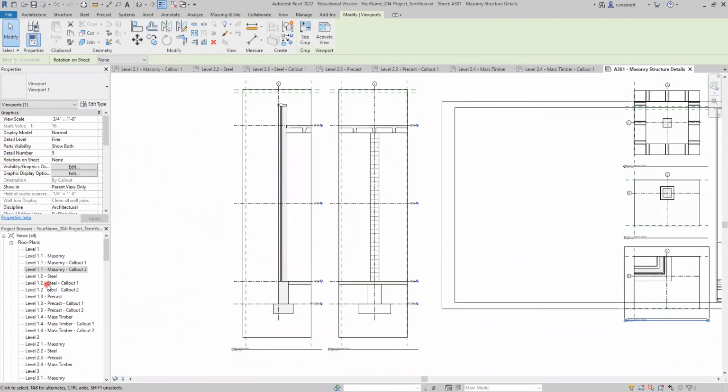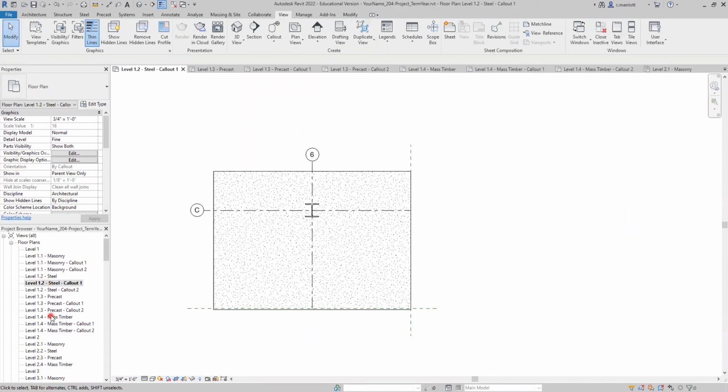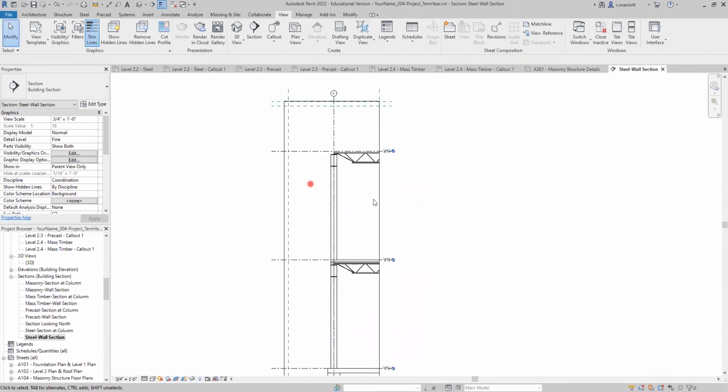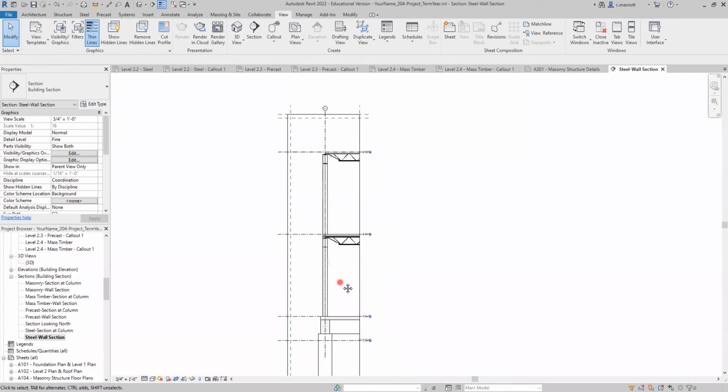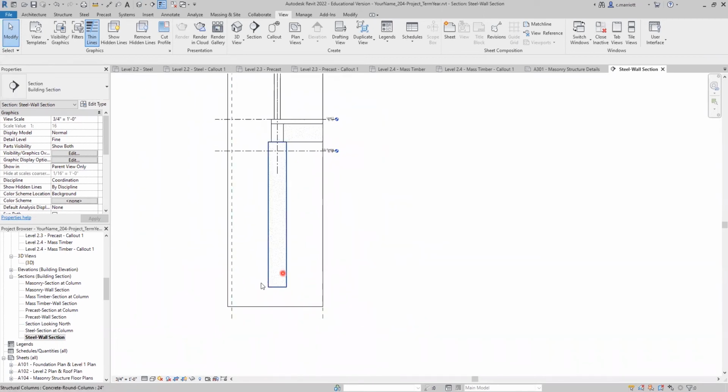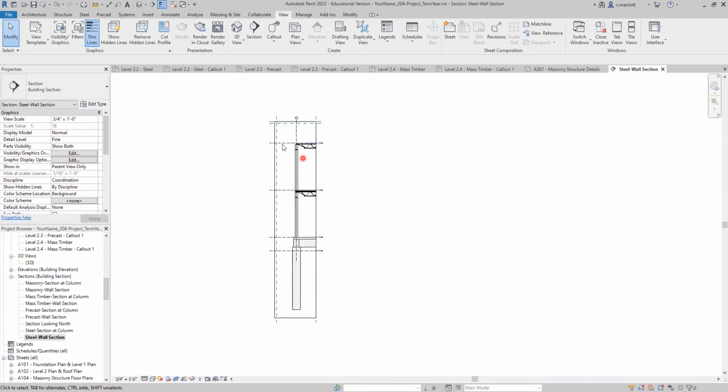If we were to look at the steel callout, actually, let's go to the wall sections here. Sections, steel section. Let's look at the steel wall section quickly. We have here one set of detail notes that's going to be for where the roof comes into the wall, one where level 2 comes into the wall, one at the top of the foundation where the grade beam is and the caisson. And then we want to capture just a teeny bit of the bottom of this so that we can show all that. So we'll have actually 4 kind of sub details for this wall section.